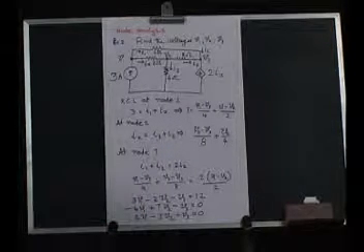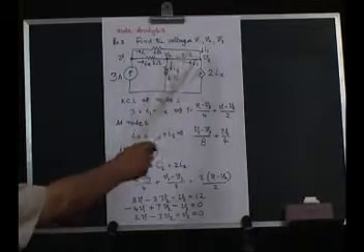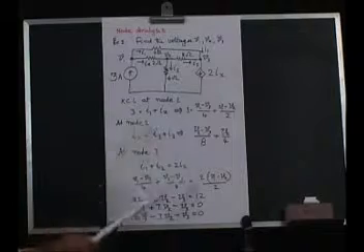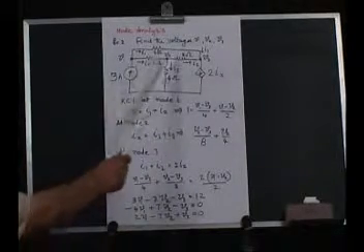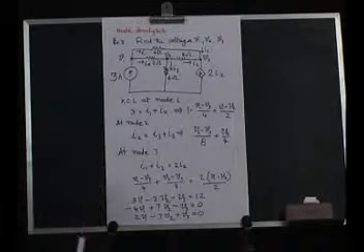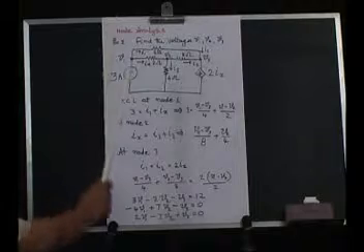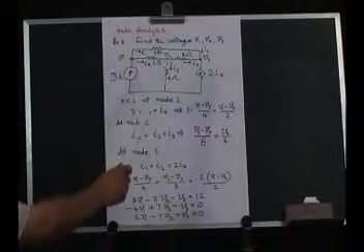Now, we shall write the Kirchhoff's current law equations at node 1, node 2 and 3. We get 3 equations and we simultaneously solve all 3 equations, so that we get the values of V1, V2 and V3. Let us see at the node V1, what are the currents coming in and what are the currents going out.